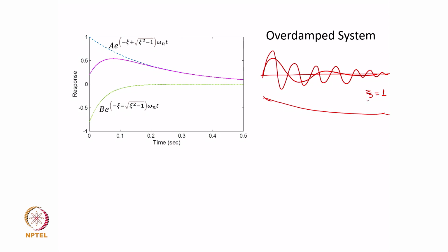There are other practical issues. If a fluid viscous damper is being used, then over a period of time the viscosity changes, there are dirt and dust, and then the overall damping value will change. It will also change with time and with temperature. So, those issues need to be addressed for choosing an appropriate value of the damping factor.